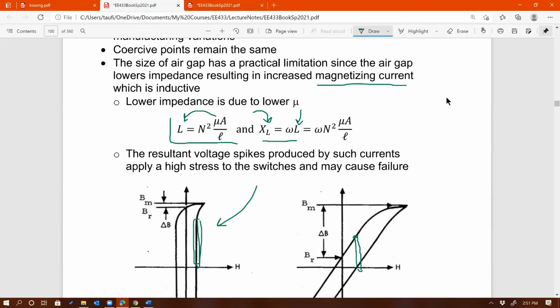They're not exactly the same, sorry. Remember these, but they're related. This model right there of a real world transformer. Here's the excitation current, I_EX, and here's the magnetizing current, I_M, right?